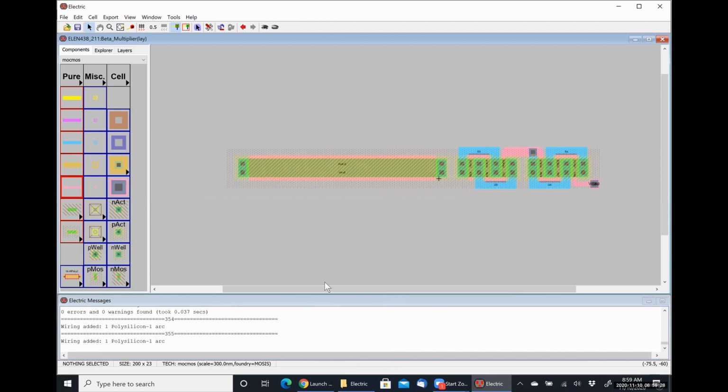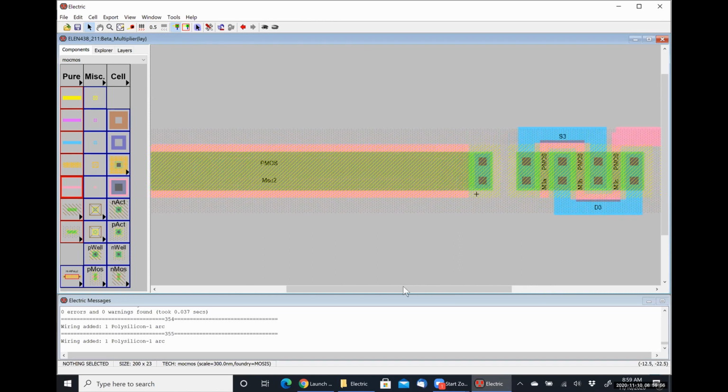I'm trying to think. I'm going to have to jump over my guard ring to connect the drain of all of those transistors to NMOS transistors. And I'm going to have to jump the gate drain connection of my really big one as well. So let me go ahead and establish that.